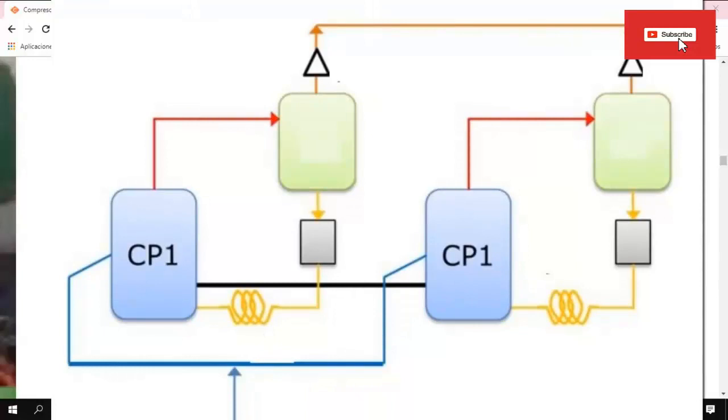3. The oil balance line is installed to prevent one compressor oil level from being much higher than the other. 4. One more sight glass is installed on each compressor to observe the oil level inside each one. 5. When only one compressor is running, the oil level of both compressors is within measure and the oil level of the running compressor is higher than that of the standby compressor, due to lower pressure in the running compressor. 6. When both compressors are running, the oil level is high under all conditions.